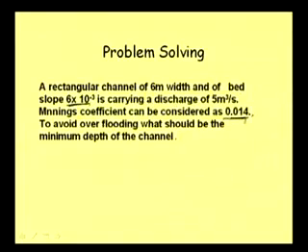And of course, when we say that the slope is this much in a man-made channel, in the topography definitely there will be ups and downs, and if in that channel we want to go by the average slope, then there will be some cutting and some filling anyway. Now, when we say that the bed slope is this much, it is the average bed slope that we define, which we get after some cutting and filling up in the actual situation. So this is the bed slope.